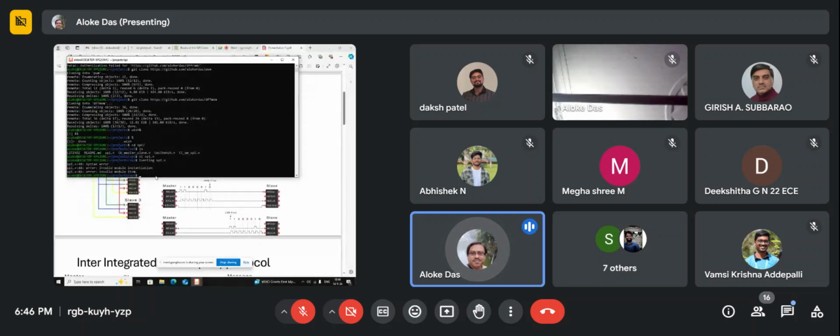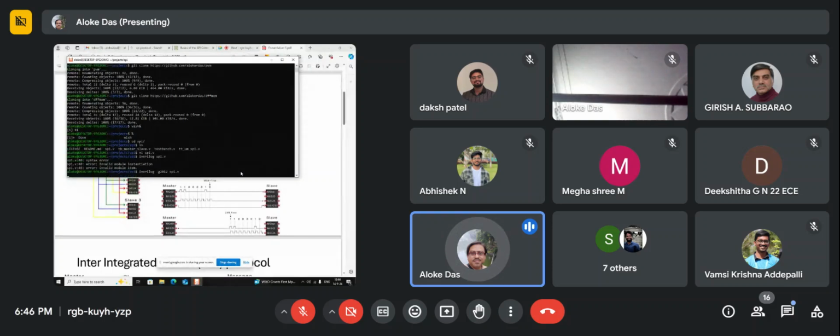When you save, your code is working. See, there are no errors. That means your design is fine. But if you want to simulate this design, it will not simulate, because we have not added the input and output, we have not forced any values. So nothing will come.